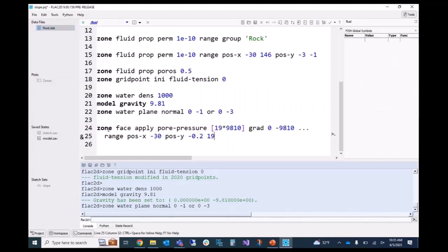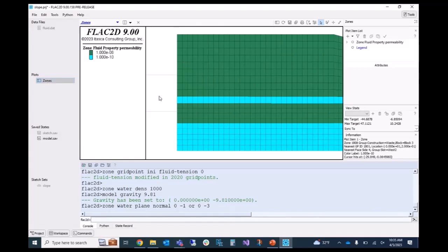So when you give these pore pressure boundary conditions and initial conditions, I could say zone initialize pore pressure, and it would be the same thing. What it does is, I'm sure you talked about this already, you give the value of the pore pressure at the 0, 0 coordinate, okay? And in this particular case, the 0, 0 coordinate is the bottom of the waste, not including this impermeable layer, right? So basically what we want to do is specify the pore pressure at this point.